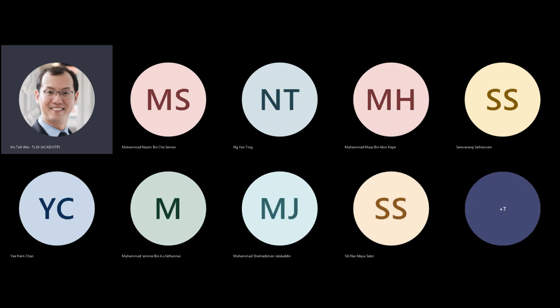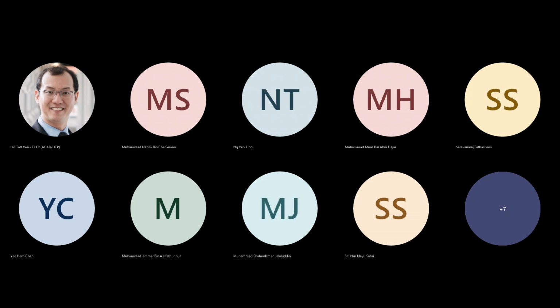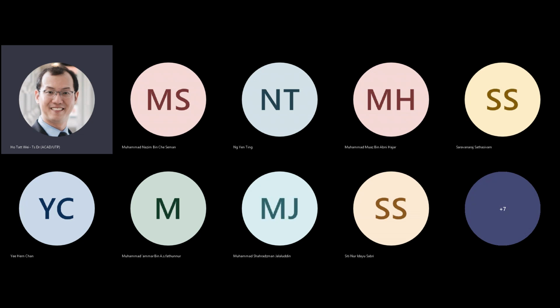So bear in mind, there are various ways you can build a digital logic gate, right? So there's a logic called the NMOS logic, right? So this is a resistor, and this is an NMOS transistor, and this is VDD. You can build logic gates like this as well, but nobody does this anymore. Why? Because this is always sinking current. This is a huge power sink. It's not efficient for devices.